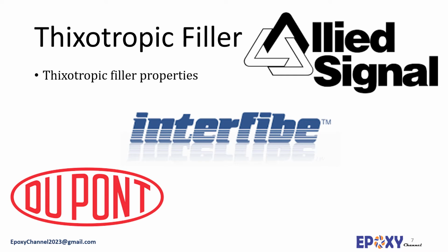A good thixotropic filler usually has the ability to interact with the polymer matrix via dipolar and/or dispersion interactions and the ability to achieve polymeric entanglement. Fibers with branch-like fibrils with high surface area and surface activity can promote rheological effects. Cellulose fibers, for example, Interfibe RT cellulose fiber, are perhaps the best examples of these thixotropes. The cellulose fibers' low specific gravity, 1.1, relative to other filler materials also contributes to weight saving and further improves the sag resistance of these systems.